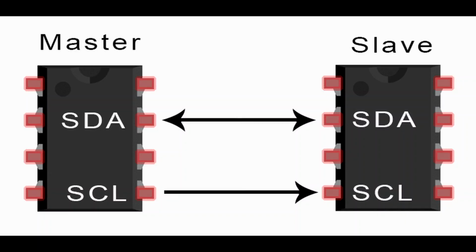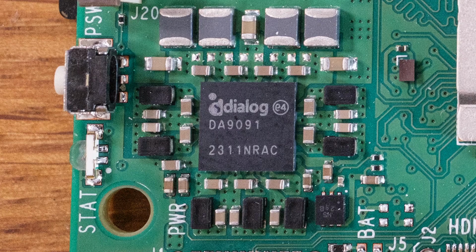Now, regular viewers of this channel will know that we very often rely on this I2C interface to work around certain overclocking limitations. And more often than not, we rely on the Elmor Labs EVC2. The first challenge is to identify the relevant I2C pins, SDA for data and SCL for the clock. This was quite a challenge because those pins are not directly exposed on the PMIC. They are in fact hidden underneath the package.